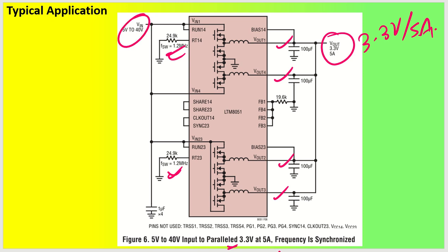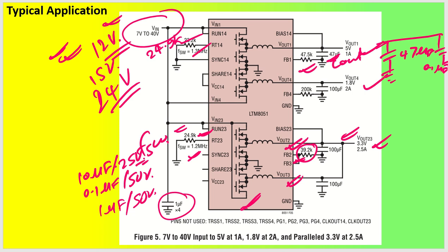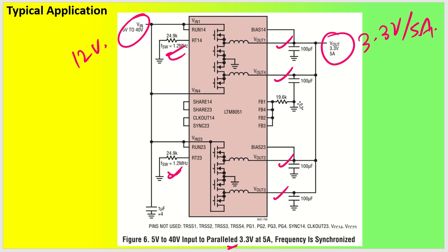I am not going to explain again and again. Here let's say we are going to give 12 volt. Similar to that, you have to keep the input capacitors as I mentioned in the previous example just now. And here you can see there are a total of 400 microfarad capacitors plus 0.1 microfarad, and if you want, you can increase by 330 microfarad additional. Okay, so let us say one more 330 microfarad. Only one capacitor should be enough to have a proper power bank. Okay,